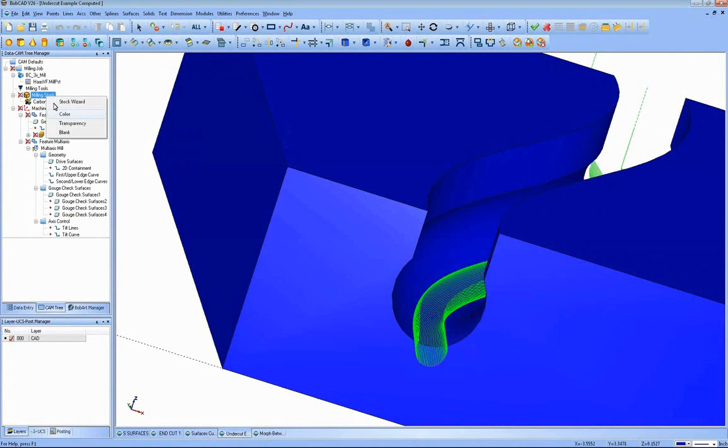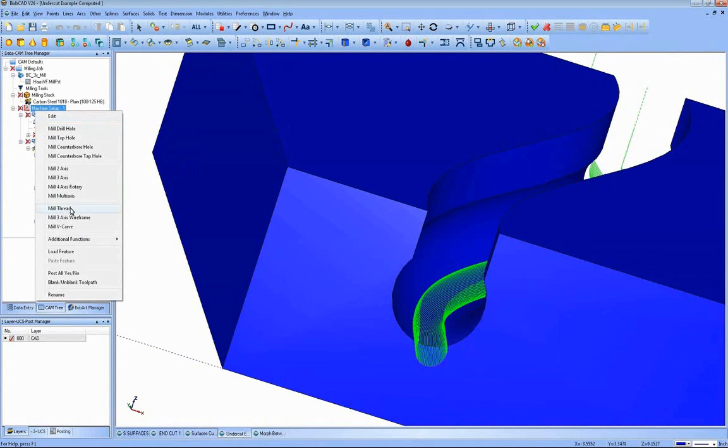What this toolpath is, it's similar to the 3-axis wireframe or 3-axis engrave, where the tool will follow the cut path, but it will take into consideration the tool, do the offsets for you and everything else like this toolpath will not. So it's a very handy method for doing custom movements, designing your own toolpath that you want the tool to follow and such. I'm going to show you an example of that now.